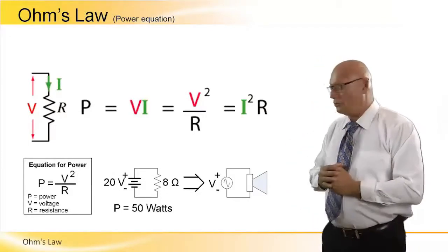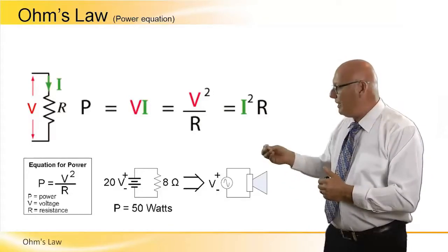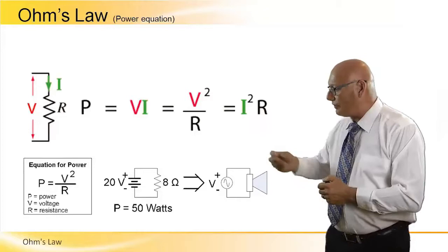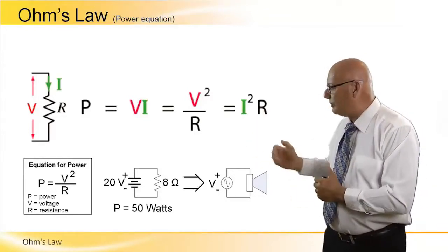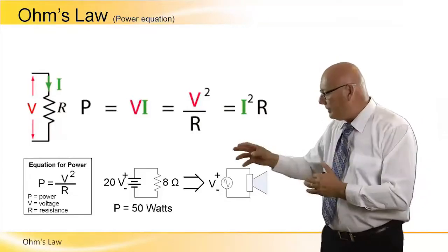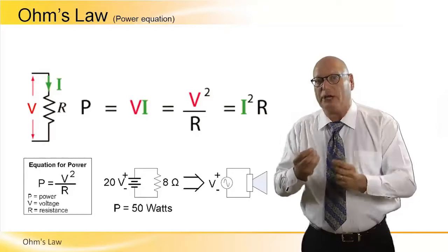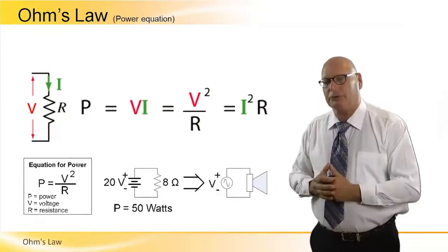The very basic one, look. We have the very basic circuit on the left, P equals V times I. Also, you can look at it as V squared over R. And in addition, like we've seen before, I squared times R. All these formulas are identical. It depends on which parameter you have a value for, so you plug that value into the formula.